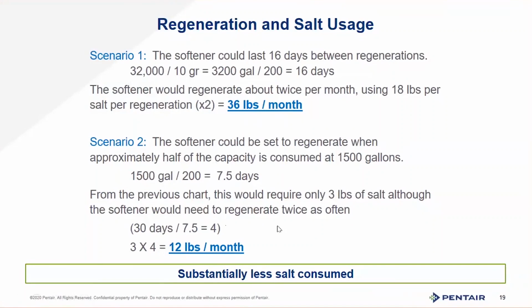So depending on water cost and salt cost, you're going to pick that on that curve. What is the most cost effective? That's why that 9 to 10 pound range tends to be the best balance between salt use and water use for cost. Okay, I pay for water and sewer. I regenerate at 9 pounds of salt. I'd rather use a little more salt, regenerate less frequently because I'm paying for my water.